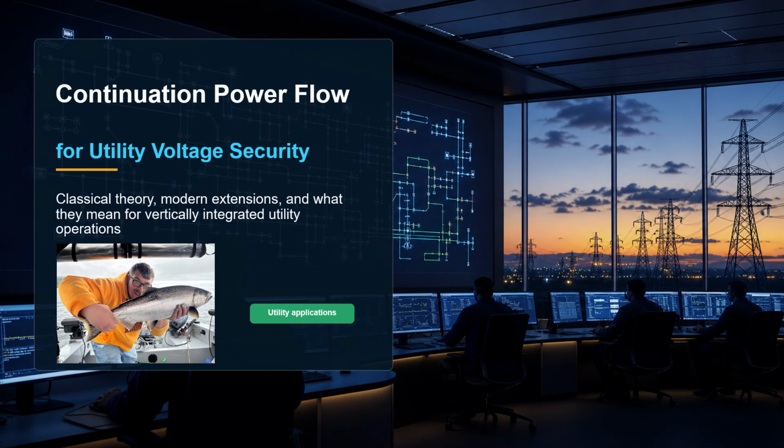And today I am presenting Continuation Power Flow, or CPF, as a voltage security tool for utility applications. The main idea is that CPF is not just a way to create a PV curve. It is a method for turning voltage stability behavior into usable operating information. For example, margin, weak locations, limiting contingencies, and possible control actions.